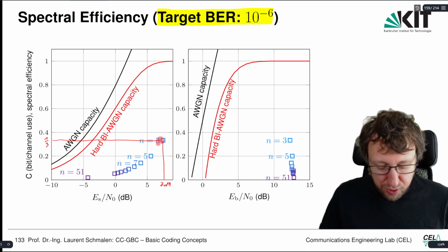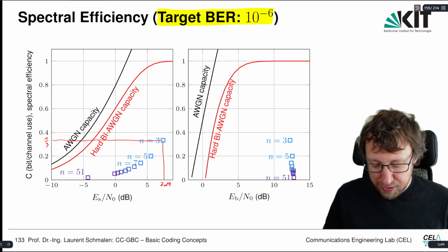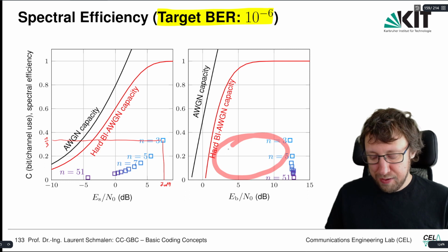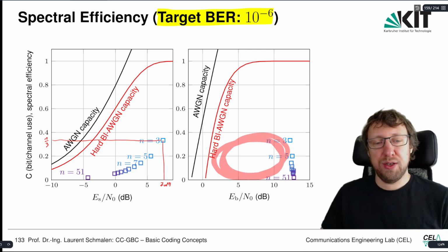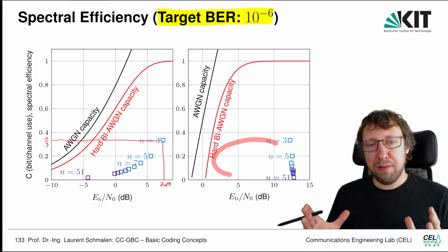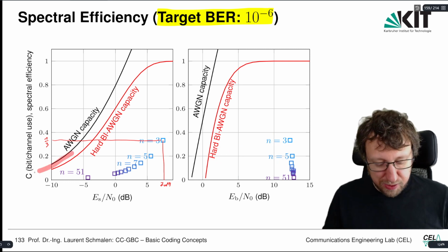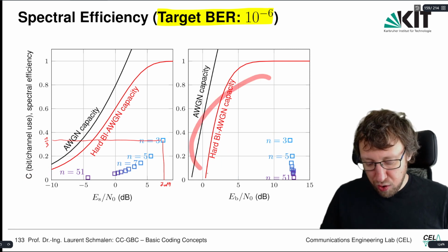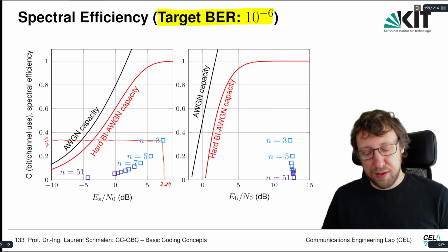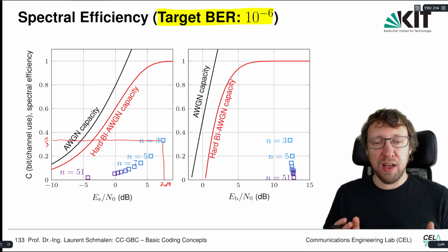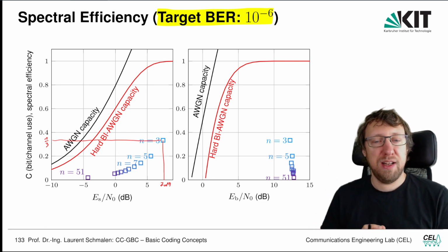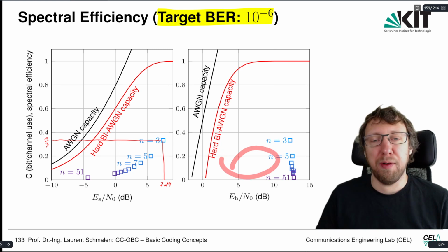So then we can take those dots, and we can also calculate the Eb/N0 for each of the points, and then we get these points. And then we see that also here we have this big gap to this region. This plot is a little bit more compact because this one tends towards minus infinity, and this one is more compact because it is saturating at minus 1.59 dB in this case. So that's a little bit better for plotting something in a box. That's one of the advantages of this type of plot as well.